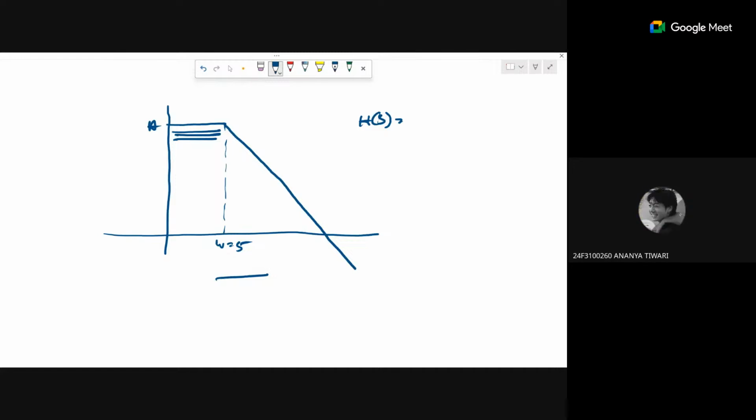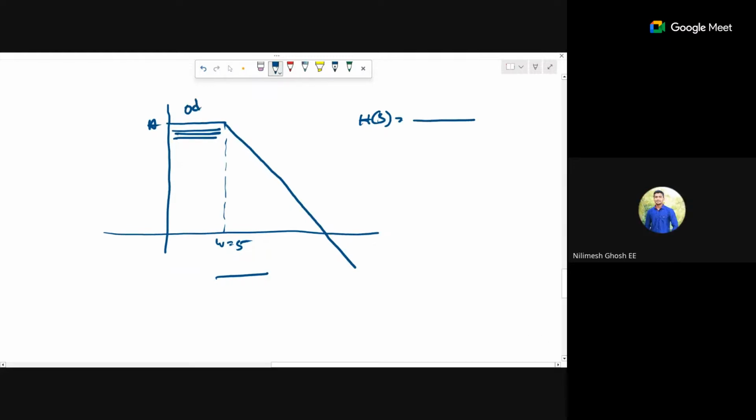There is A. So this signifies that there are no poles or zeros at the origin, at s equal to 0, because the initial response is flat. This means the slope is 0 dB per decade, and then this is minus 20 dB per decade. Yeah, I should mention the slope also.